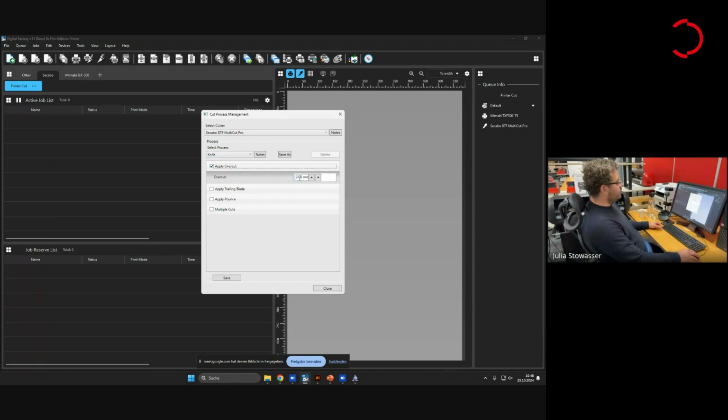I want an overcut. Overcut is really important when cutting DTF film, because as all of you might know, when the DTF film comes out of the oven, is powdered, it's not going to be 100% flat, and even it's going to have all sorts of tension inside of the material, which makes it a little bit more difficult to handle. There will be a lot of smaller or bigger waves and tension within the material.